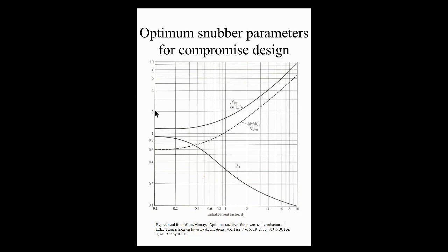So you locate that 1.5 and you come across. To get the sigma, you come all the way down to the sigma curve, and wherever you hit that curve, you go across and read off the value on the y-axis, and that will be your sigma.